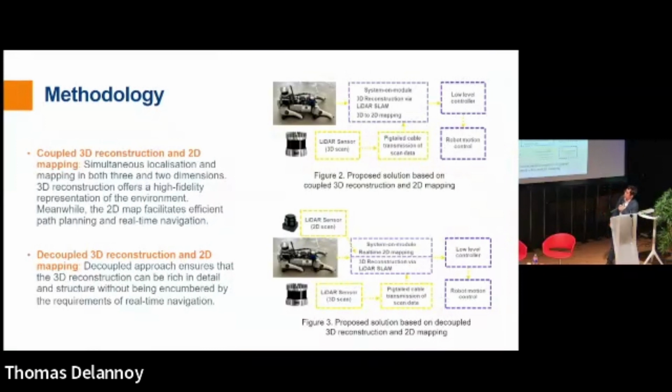In our method, we also take two scenarios. One is called the coupled reconstruction and the other decoupled 3D reconstruction. The decoupled reconstruction is where we use 2D LiDAR and 3D LiDAR separately: 2D LiDAR doing its own job for the navigation, and 3D LiDAR doing the 3D point cloud capture. Then for the coupled reconstruction scenario, we mute the 2D LiDAR. We purely use the 3D LiDAR for both the navigation and the 3D reconstruction, and see if we could save the cost of another LiDAR.